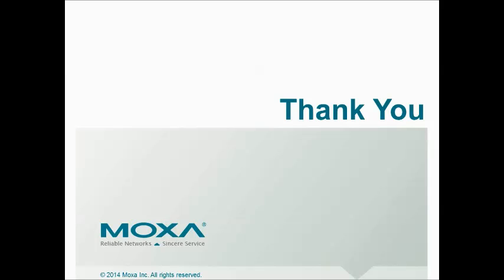All right, thanks, Ron. That's an excellent question. So yeah, that distance definitely is line of sight. I assume you're talking about the 10, 20 kilometers that we talked about in terms of wireless distance. Those distances do need to be line of sight. Unfortunately, Wi-Fi doesn't have the ability to penetrate buildings. So when you're going those distances, it tends to be good for applications that are outdoors in free space. So whether you're talking down an oil pipeline, if you want to talk to an offshore platform, or if you have a remote location at the top of a hill or at the bottom of a valley, you have clear line of sight to those areas. That's what Wi-Fi tends to be good for.